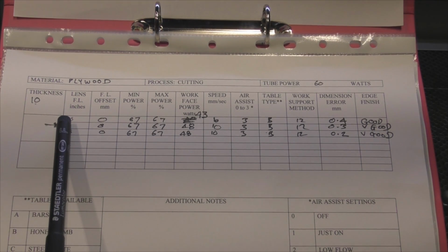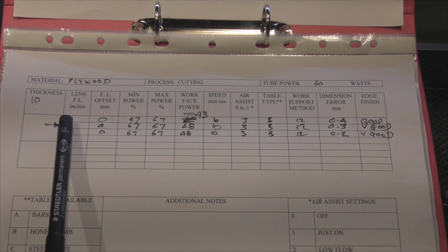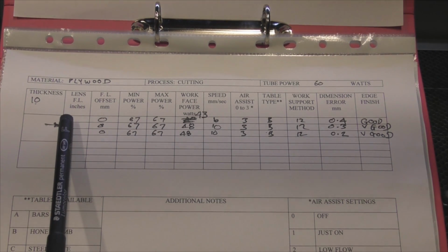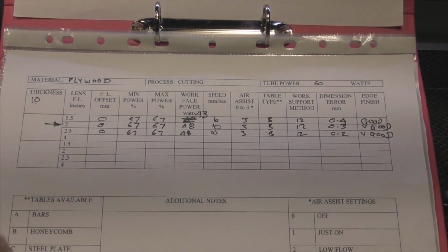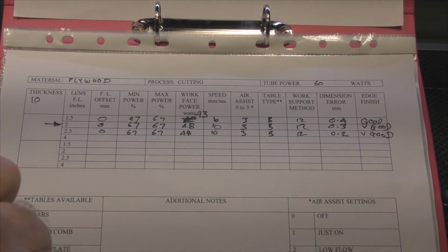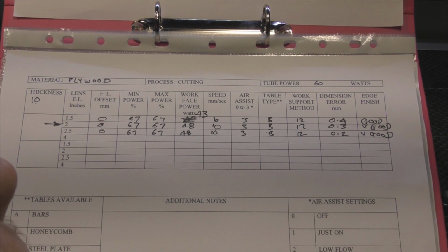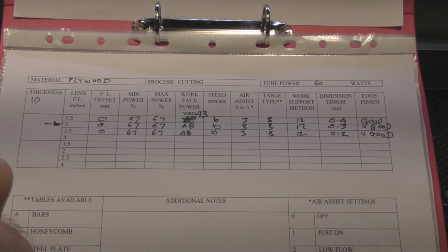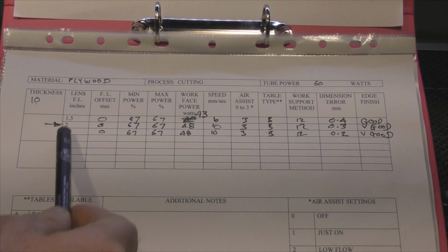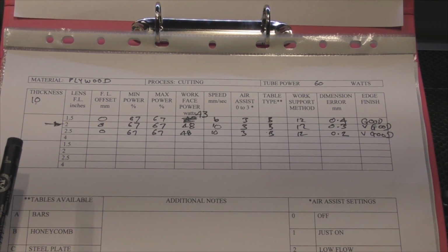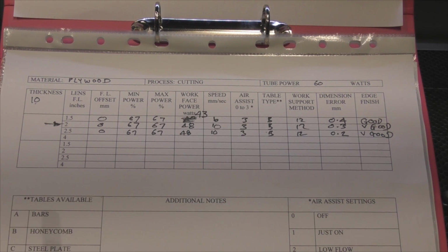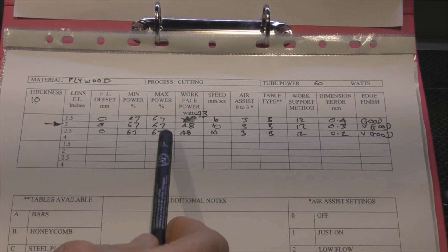Okay, well, we've finished up with our final set of results for plywood, which was the 1.5 inch lens, which we thought might be a little bit hopeful. It was hopeful but interesting and revealing. We found that the best results, surprisingly enough, was at 0 offset. Now, all the books and everything will tell you that I should have had that lens probably set 2-3 millimetres into the material. Same with these lenses. It appears not. Now, that may be a unique property of plywood. I can't say.